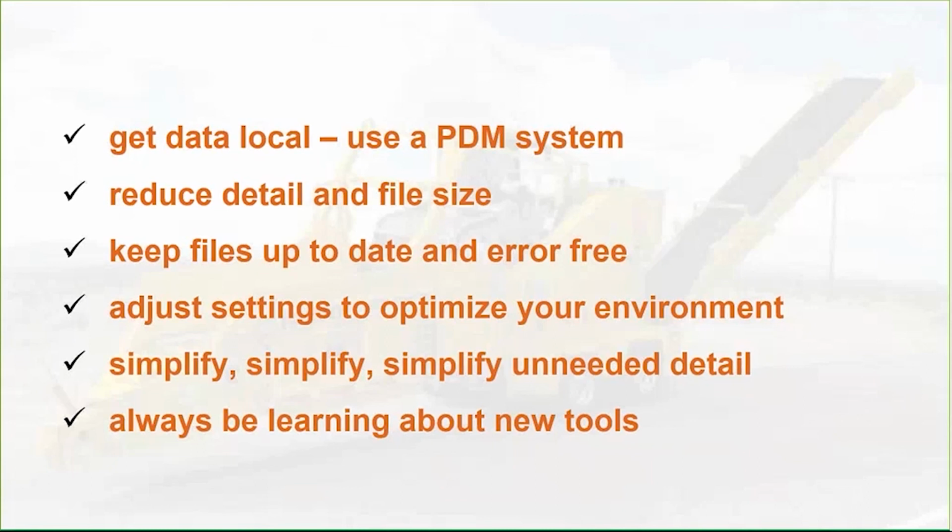Simplify, simplify, simplify, right? It's probably the biggest check mark on here that you can completely control yourself. That's why I maybe mentioned it 3 times there. Definitely try to simplify the geometry for the large assembly usage, right? Definitely helical items like springs, fasteners, that's a big no-no at the large assembly level, even at a moderately sized assembly level. So you've got to go and create some simplified configs of those things.